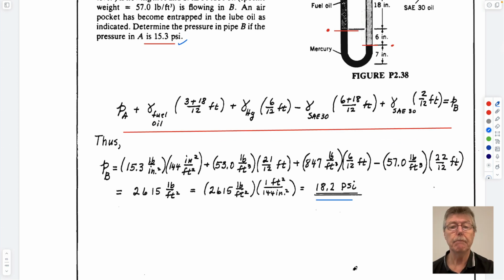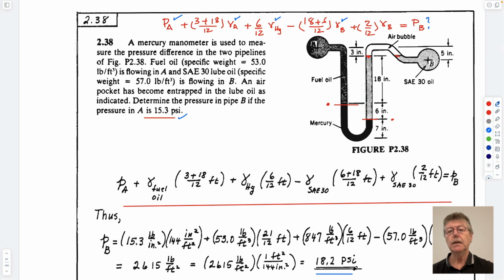Yeah. So the air bubble really doesn't contribute to the pressure at all? No, I think the best analog is that Tygon tube turned upside down. Was it you who asked the question of how thick the manometer tube should be last time? Yeah. So you want the manometer tube to be thin enough that a bubble can't pass up it, but not so thin that you have capillary forces applied at the meniscus that affect it.